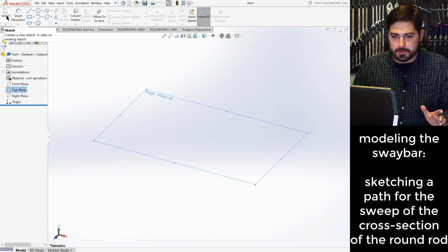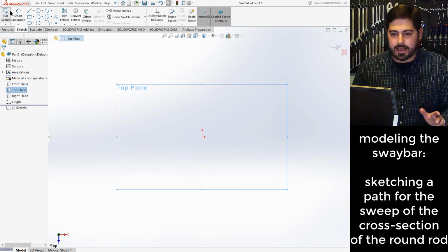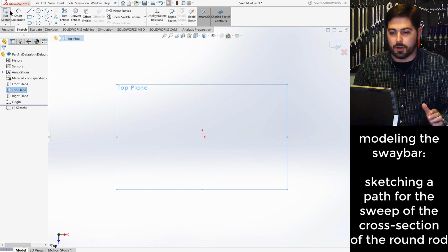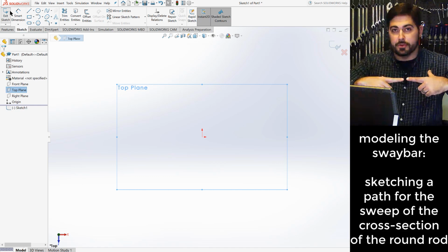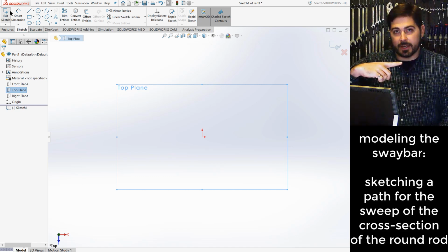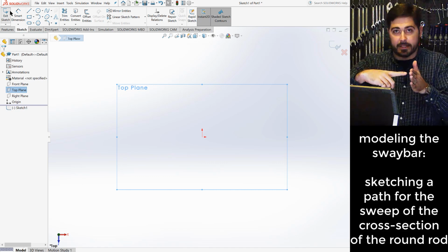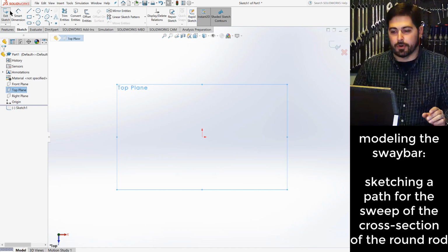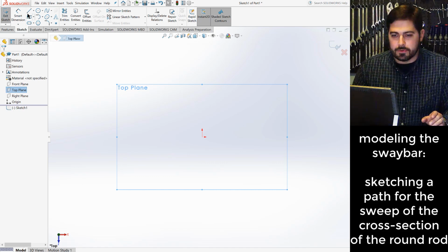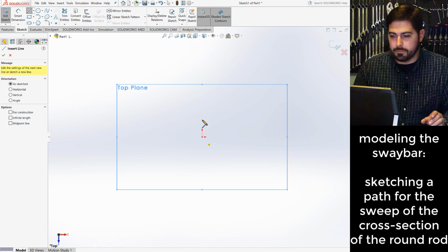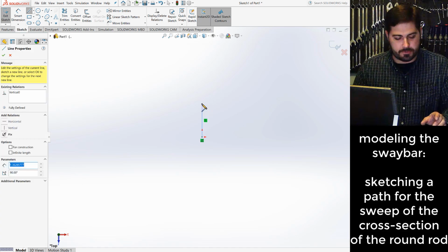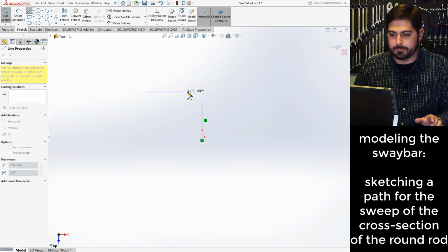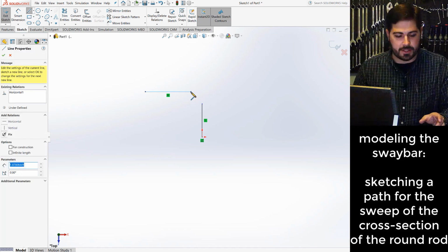Okay, so start a sketch. Actually, let me explain this too. First of all, I'm going to make a model not of the entire U-shaped piece, but only half of it, because it is symmetric. The way I'm going to make it, it's going to be symmetric across a center plane, so I'm just going to make one half of it and then mirror it. Let me start with just a portion of this path that goes right here. I'm then going to put a second portion of the path that goes up here. Okay, so far so good, pretty easy.